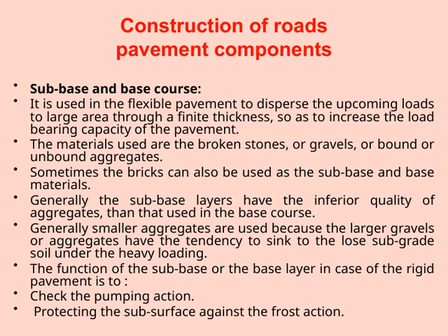Another key point is that smaller aggregates are usually preferred in these layers. Larger gravels tend to sink into the underlying soil when subjected to heavy loads, which can cause unevenness or instability. Smaller aggregates help maintain the layer's integrity and stability under traffic.